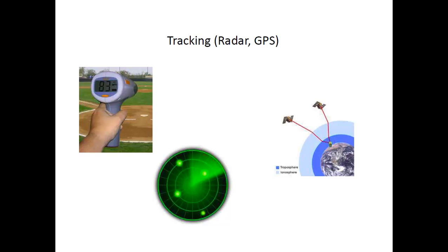Beyond just inferring those things that I mentioned, you also might want to track an object over time. So you'd say, well, if your radar signal said it was at a certain position and velocity at one moment in time, and another moment of time it's in an inconsistent position and velocity, then you would use some sort of smoothing technique, which is another signal processing application, to track and remove whatever noise is possible out of your radar. So the material we're learning in this class directly applies to this type of technology. Absolutely.